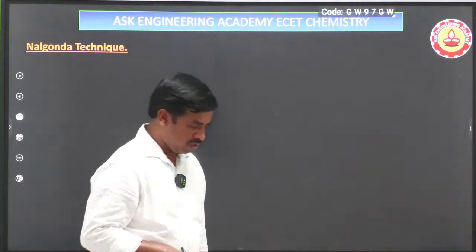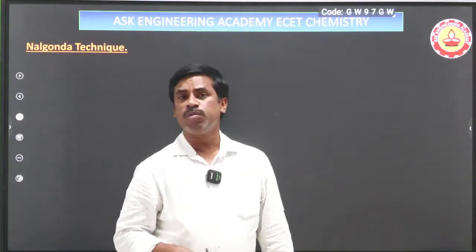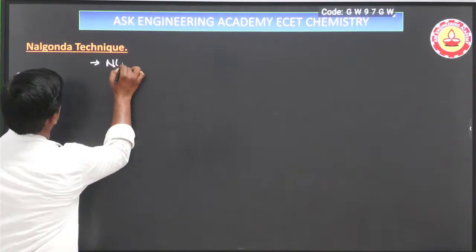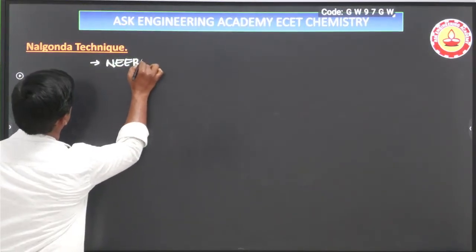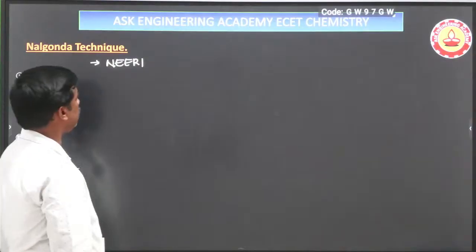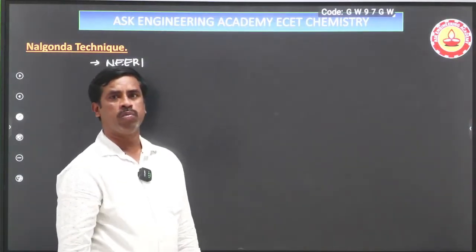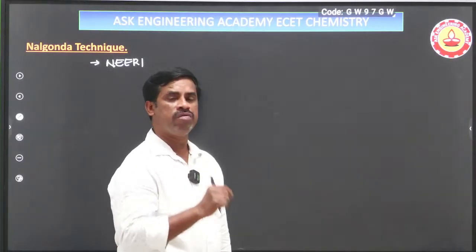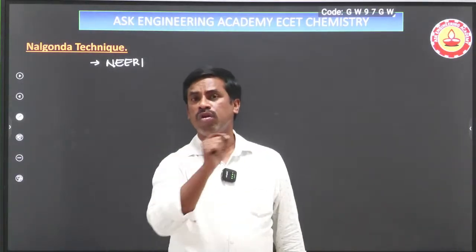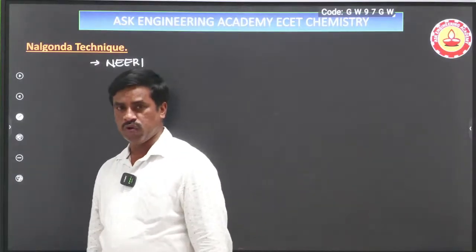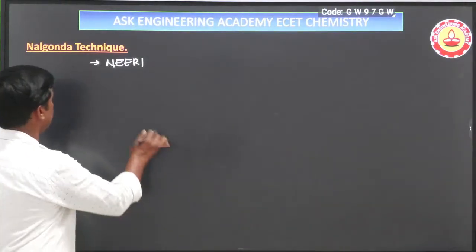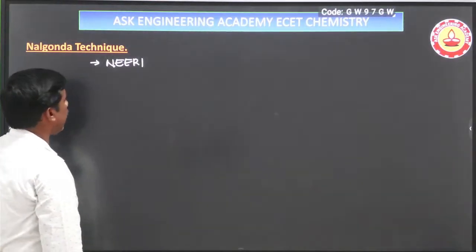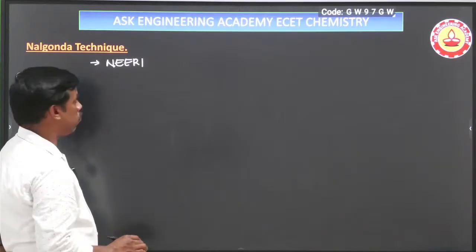Nalgonda technique. Here the Nalgonda technique was developed by NEERI, the National Environmental Engineering Research Institute, Nagpur. What is the main aim of this Nalgonda technique? To remove fluorine from water. The Nalgonda technique explains the removal of fluorine from water.